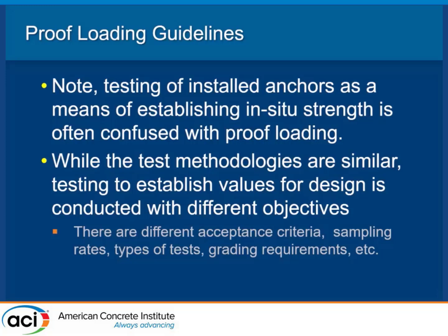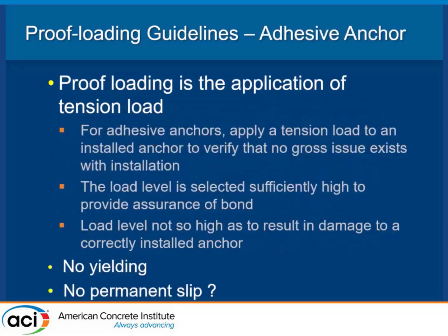And so you hear about proof loading a lot. So I kind of threw this in there a little bit. And so proof loading, well, what do I do if I want to proof load? What proof loading is, we just want to make sure the anchors were installed well. We're not trying to establish that these things can handle the maximum load. Okay, so that's not the objective of proof loading.